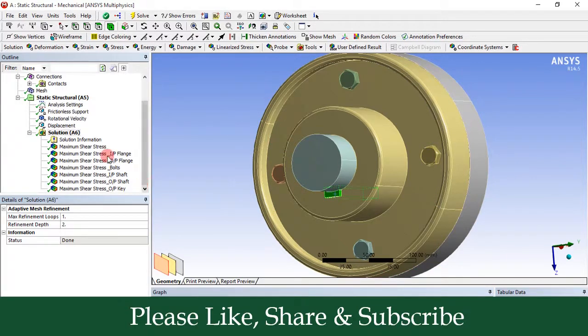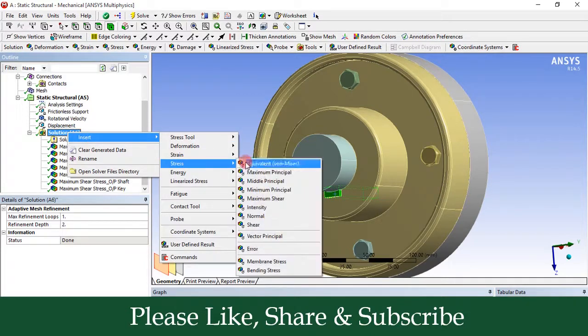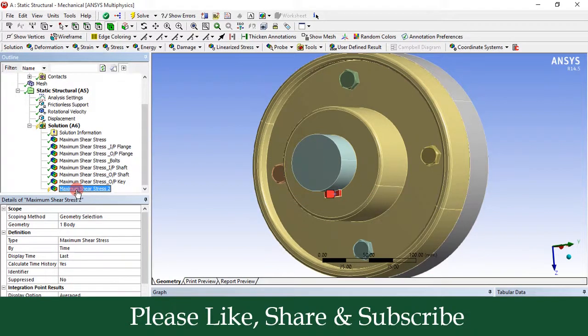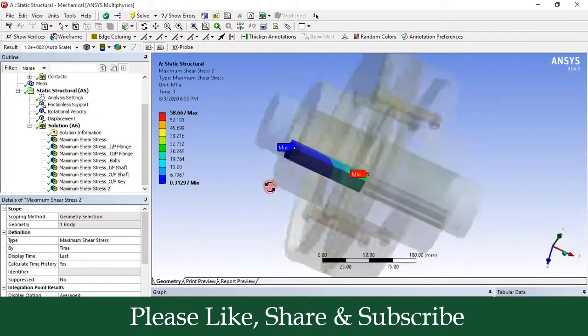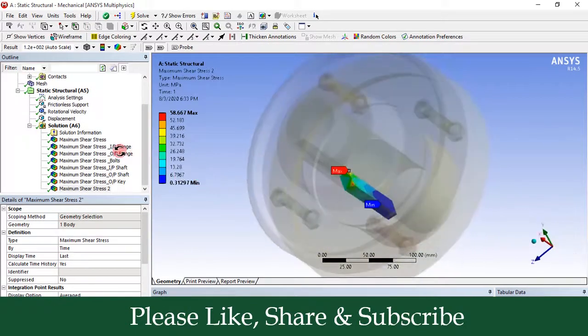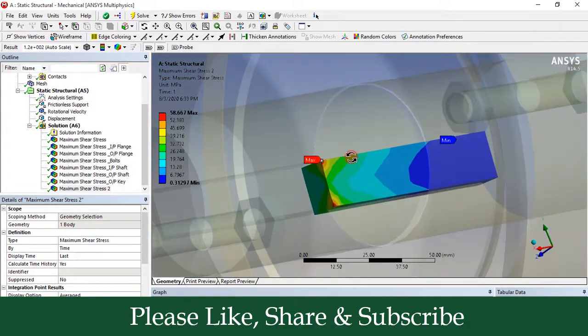So key is selected. Now let us left click on solution, right click on solution, go to the insert, go to the stress, go to the maximum shear stress, then right click on this maximum shear stress and click on evaluate all results. So you can see the solution for this input key is ready, and you can see clearly the point of maximum shear stress for key.